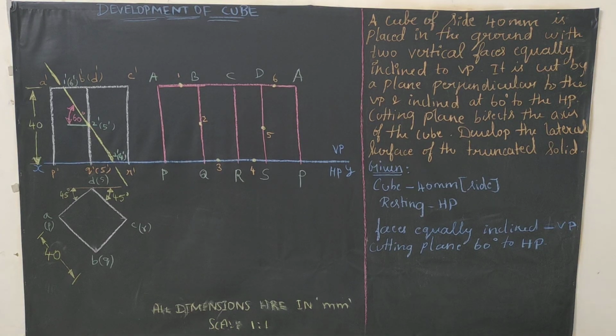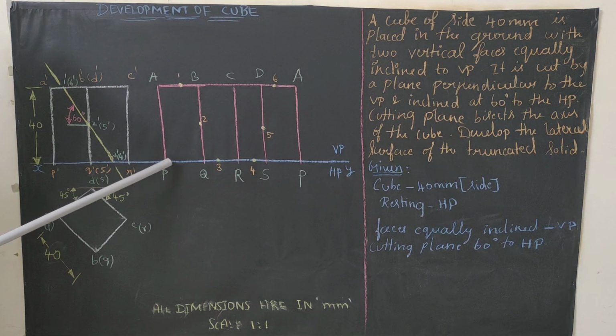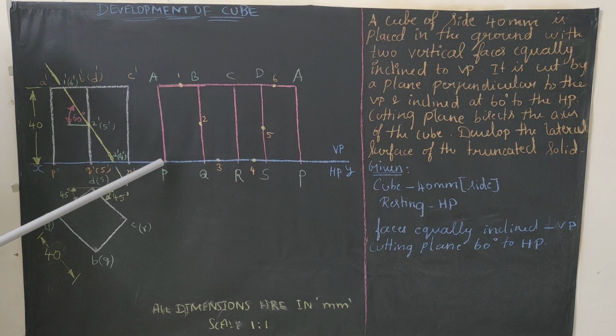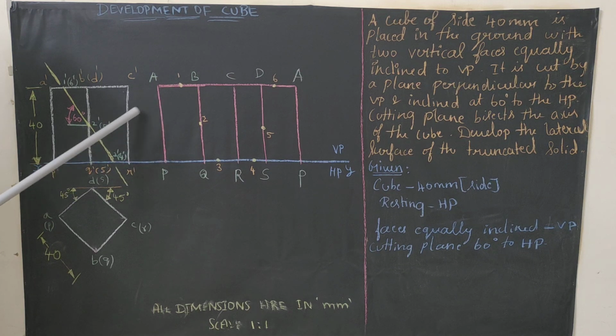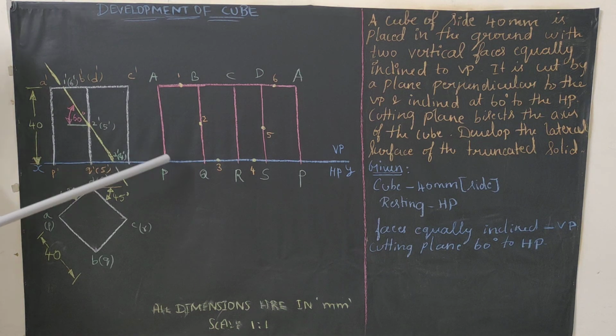The next step is just identify the cutting points. So I use the parallel line method. So from here, from here for 40 mm. So height is 40, right? Same 40 will be having. You can leave 2 or 3 centimeter gap between the front view and this diagram. So this is our front view. Between this diagram and the next diagram you can leave 2 to 3 centimeter gap, and later on you just start with your point with your reference.